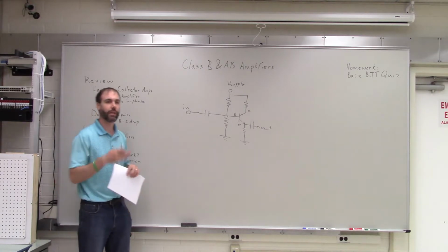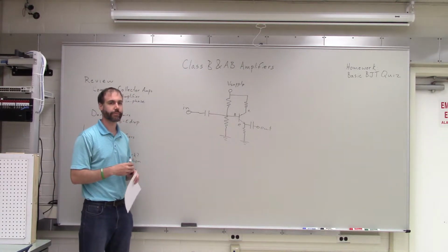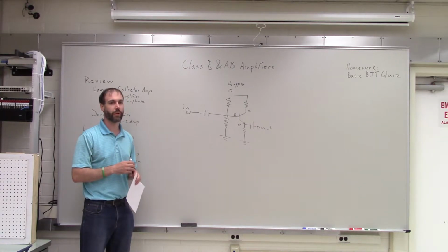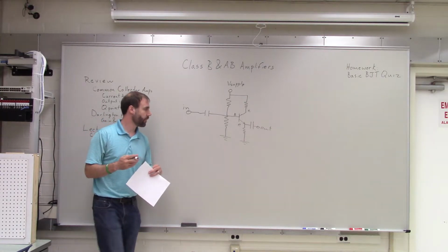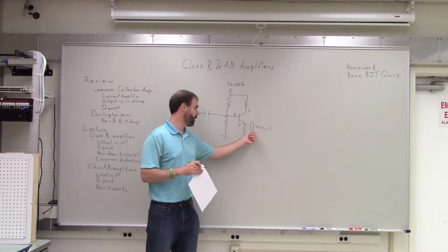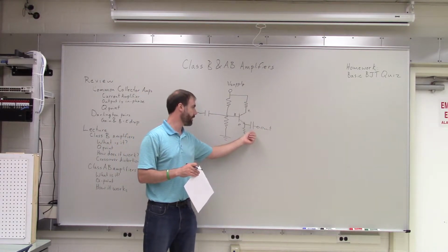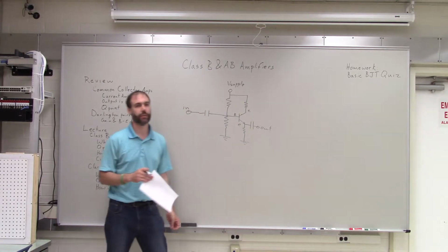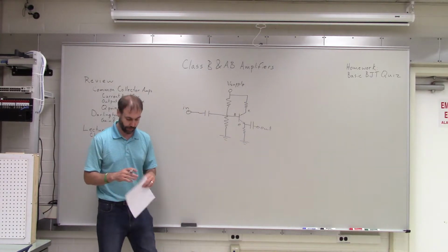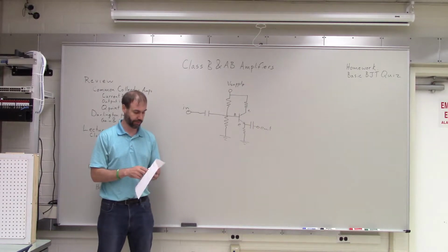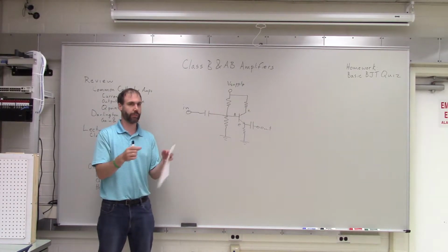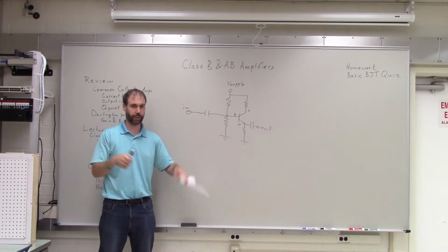You okay? Yeah. So the bigger the capacitor on the output side, it's supposed to be the cleaner the signal you get out, right? Right. Yeah. You would block the DC more effectively, and you would pass the AC more effectively. But you run into certain limitations in terms of size eventually. If you're trying to build a small circuit, large capacitors get physically big and they start crowding things out.